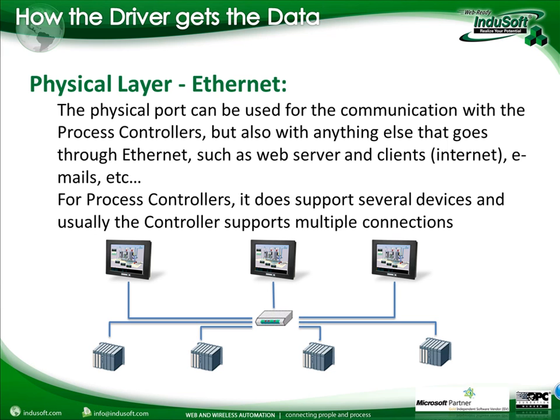And on Ethernet, you can have the same physical port doing several different things. You're not limited to only communicating with the PLC. You're probably used to using your computer to read your emails. On the same computer, you can access your web browser, and you can FTP to a remote website. They all use what? They all use your Ethernet port to do that, even your wireless Ethernet port. So the physical port can be used for several different things, unlike serial. And one of these things that you can do is talk to a PLC.